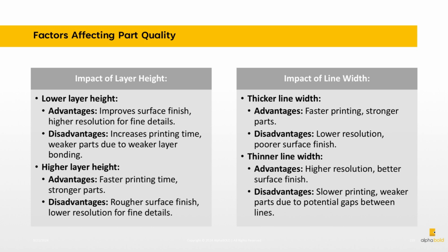Impact of layer height. Lower layer height. Advantages: improves surface finish, higher resolution for fine details. Disadvantages: increases printing time, weaker parts due to weaker layer bonding. Higher layer height. Advantages: faster printing time, stronger parts. Disadvantages: rougher surface finish, lower resolution for fine details.